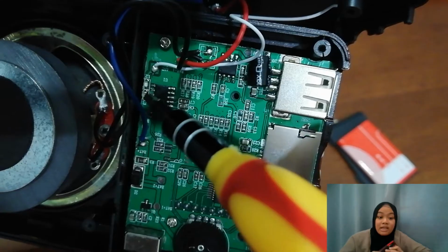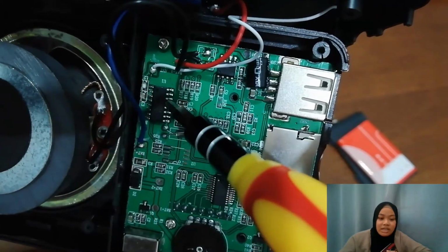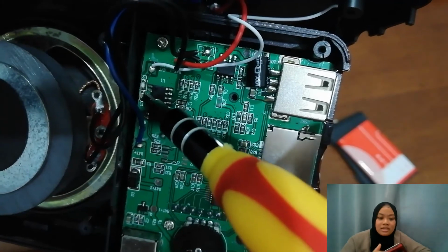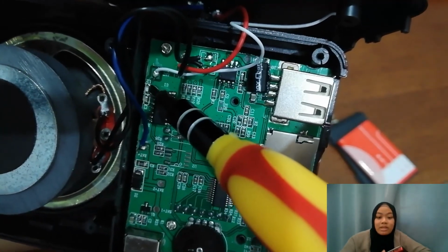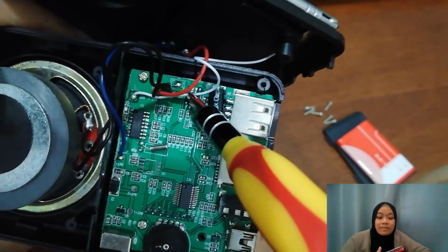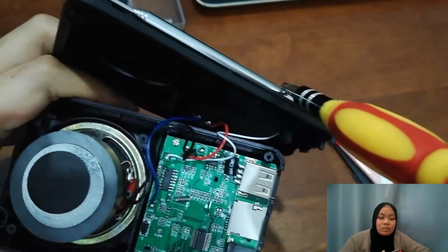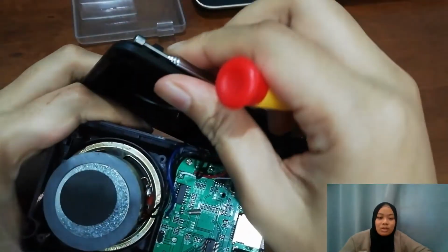Moving on, the combination of C3 and L1, as shown here, comprises a resonance circuit referred to as a tank circuit. Its purpose is to select one out of many available radio signals. The variable capacitor C1 allows for tuning to the various signals. Then it will be connected to the antenna using the white wire.